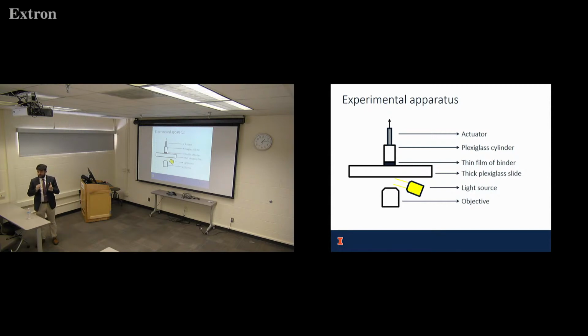For mixture, if you actually want to predict mixture cracking, you have to consider both cohesive and adhesive behavior, which means you need some kind of adhesive test. A lot of people have worked on different methods, like surface free energy, to look at adhesion. We didn't work on that part so far, but yes, you're right. You need two different methods. I think you have to characterize them separately. You cannot characterize them both in one test because there are too many variables to predict which way it's going to fail. So you can first predict the cohesive response and say, this is the ranking by cohesive performance of the binder. Then you can take your binder and aggregate material and say, this is the adhesive performance of the materials.